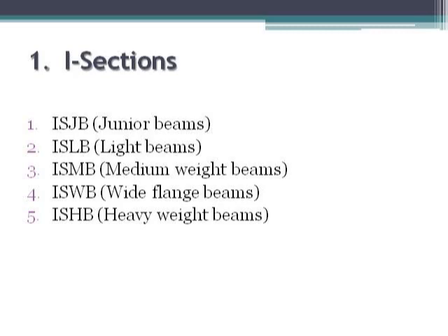Transverse loads are those which are perpendicular to the beam axis. So to support heavy transverse loads, we require more moment of inertia about the ZZ axis, that is the major principal axis.